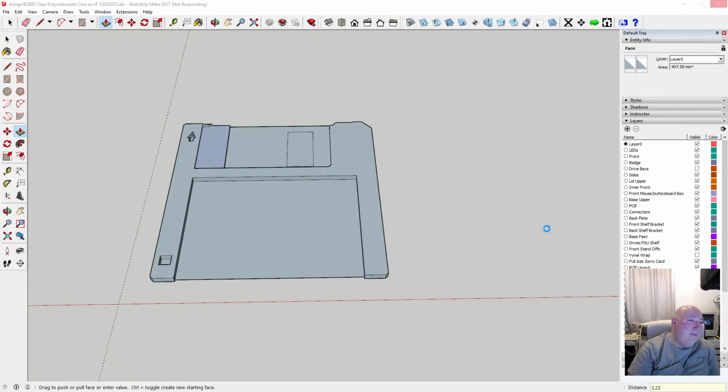Sometimes if you're making a bracket for something, a metal bracket, some people make it just good enough to do the job. Well, that's okay till you get some vandalism or abuse or high winds or something. So what you want to do is over-engineer it a bit if you want it to last. And I always say if it looks over the top, then it's right.